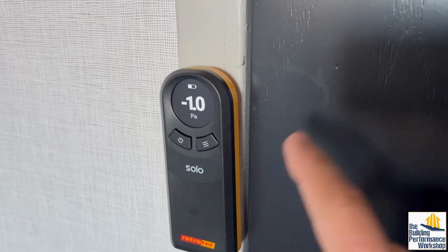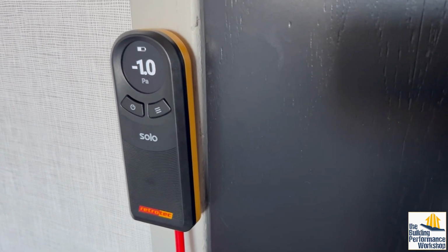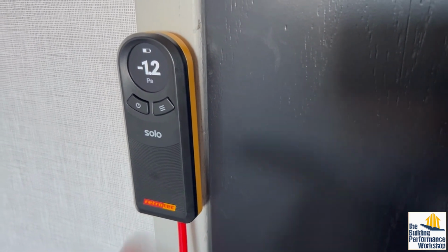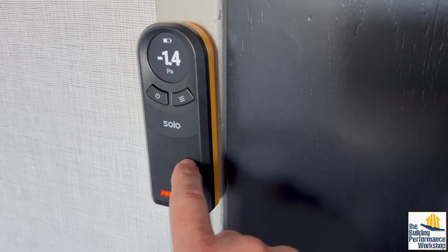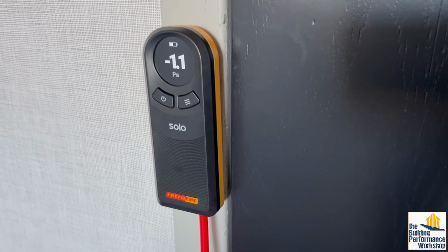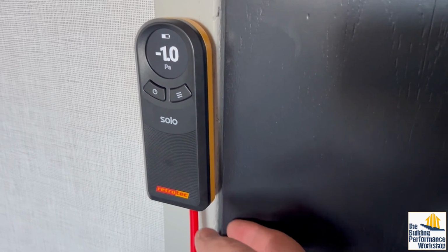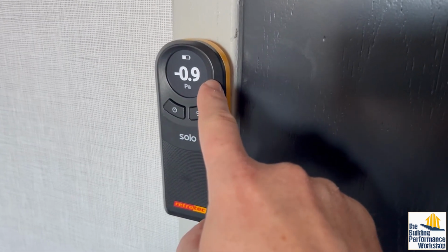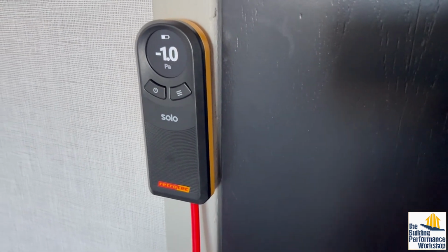And that's weird because normally a building like this would be supply plenum in the hallway. So they would be supplying for the hallway and then drawing from the exhaust fans in the units. But this one, for some reason, something out there is depressurizing the hallway, and it might be that that is stack effect at work. We are on the top floor of this building, but it's not a huge amount of depressurization. What it means is that no air is coming from the hallway into my unit, and I do like that.